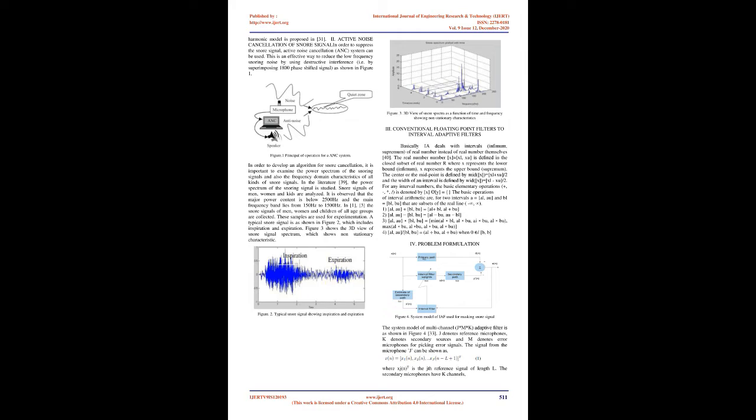Interval analysis-based global optimization methods are also used to determine the coefficients of McClellan transformation and 1D filter 17, 18. The feasibility of interval analysis method is used to verify 2D fan filters' correctness. In 19, the IIR filter is designed by using interval optimization methods, which will increase the accuracy of the design of higher-order filters. The optimally bounded Kalman filter is designed in 20, and is used for the uncertainties of sensor inputs in terms of observations and noises.